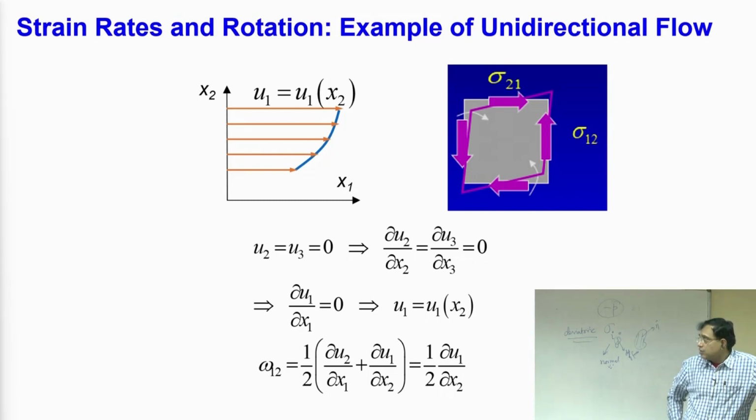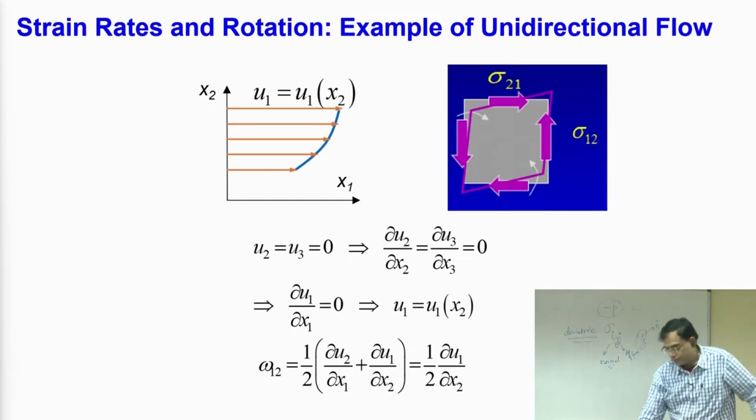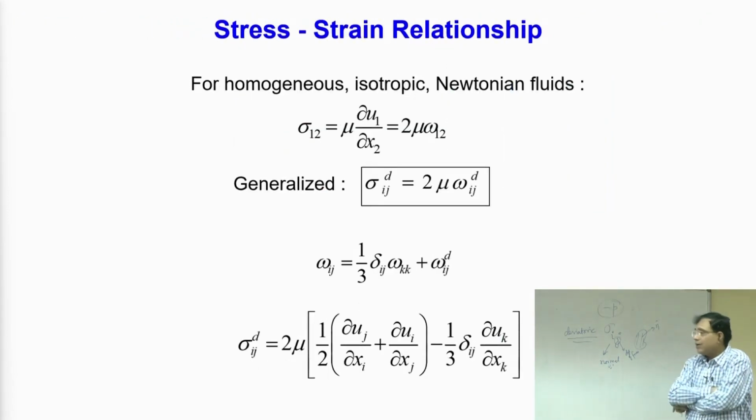So, now we can calculate different gradients, and this particular derivative which is shown here is talking about the rate of shear strain. This is just to give you an idea of what it physically means. So, you have a stress versus strain relationship which is called the constitutive relationship, and this is where all fluids are different. In the previous lecture we were talking about blood and several other different types of fluids. Up to what we discussed in the previous slide, there is no difference. It is the general description of stress.